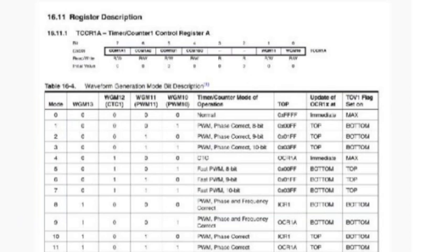So say we want to set it into fast PWM mode. And so you look down at which bits you need to set, you set those bits, and you are good to go. The other bit we're going to need to set, and I know this because it's even further in the data sheet, is one of these COM bits. So bear that in mind as we go through.